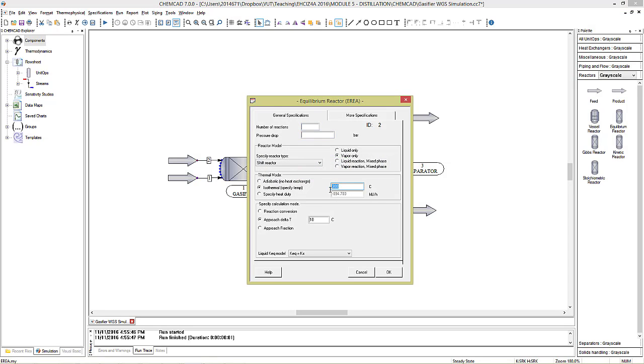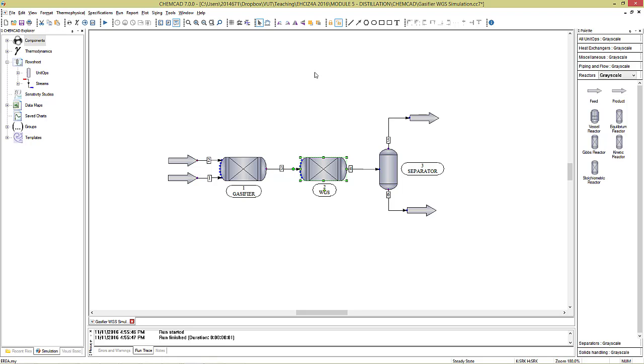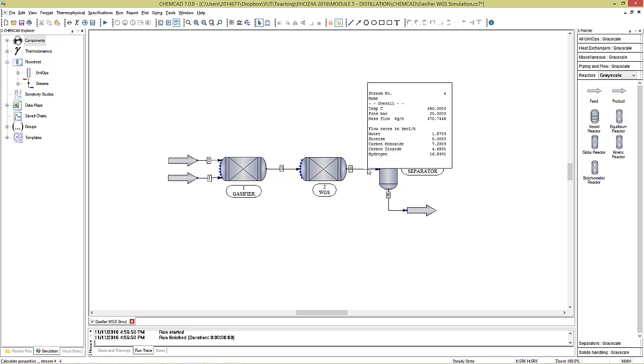I would say let's go to 450. I would usually go higher so that I pass the required point and then select maybe a point in between, but at this point I will just go sequential and say let me go 450, and then let's run this, and then we can look at this. We have increased our carbon monoxide slightly, but our hydrogen, if you look at it, the ratio is supposed to be 7.3, maybe supposed to be 14.6 for hydrogen to be right on the molar ratio of 2 H2 to CO. So we still need to ramp up the temperature a little bit.